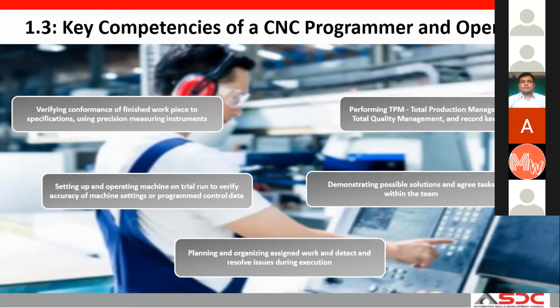Lift the tool by using the offset method, lift the tool by some suitable distance, and take the trial run of the tool, and observe while the tool is moving in the trial run. If there is any mistake, the tool is moving out of the way, not as required per the profile, then he can correct it. He should know where the program needs to be corrected.